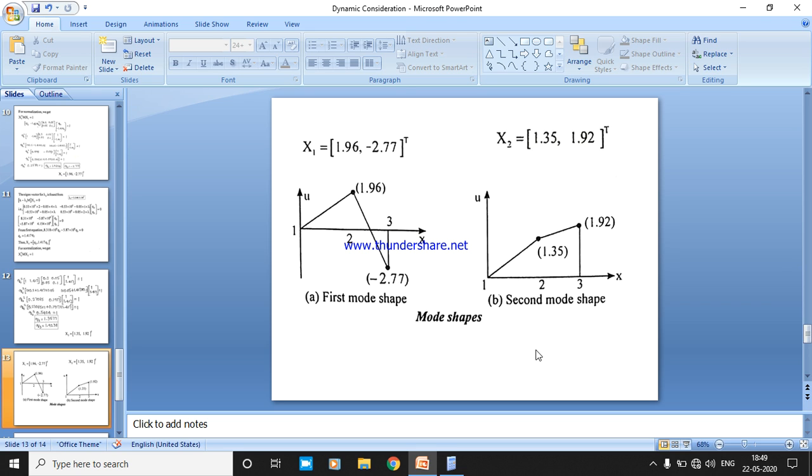Same, using the beam stiffness matrix and consistent mass matrix of the beam. So when we consider the beam, the matrices will change. For the beam, each element has 4 degrees of freedom, but when I consider the bar element I have 2 nodes. Why? The bar element is a 1D element, whereas the beam and truss elements are 2D elements. So definitely the stiffness matrix is going to change for trusses and beams. For the beam, the stiffness value K is going to change and the consistent mass matrix is going to change. That I already discussed in class 1.